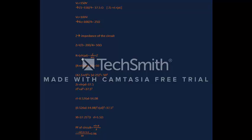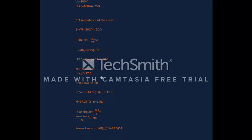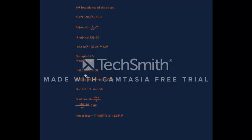Also R plus RL plus jXL minus j upon omega C is equal to Z. Solving these equations and substituting values, we get (42.5 plus RL) whole square plus (XL minus 25) whole square is equal to 50 whole square. We also get ZL equal to RL plus jXL with magnitude 37.5, so RL square plus XL square is equal to 37.5 square. By solving this, we get RL in terms of XL, and on solving further we get the equation.